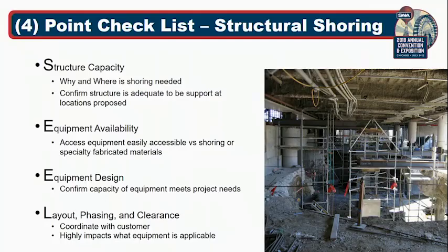The last one's going to be the layout. This is where you want to have a really clear conversation with your client, making sure you understand what kind of phasing they're going to be going through in the project, and asking if they have any clearances that they require. Because once you get your shoring system in place, moving it is a pain. So making sure you are both on the same page from the outset can make it go much more smoothly.